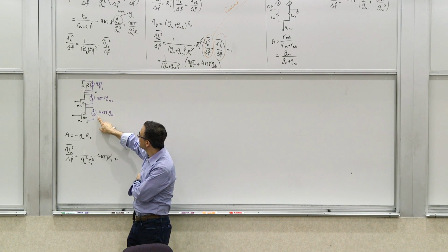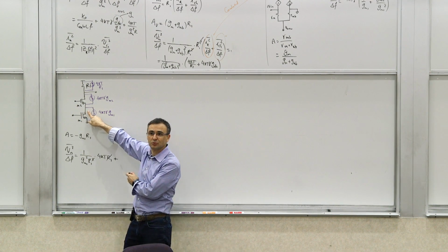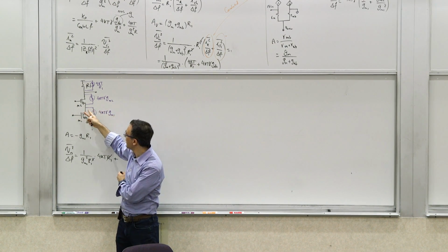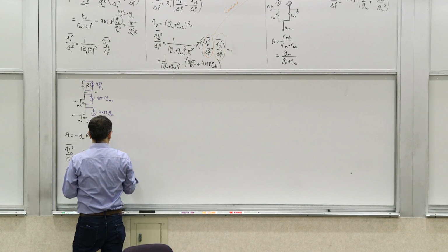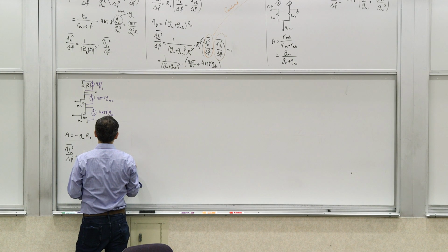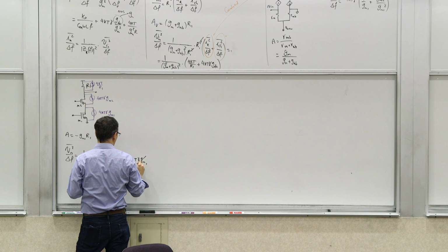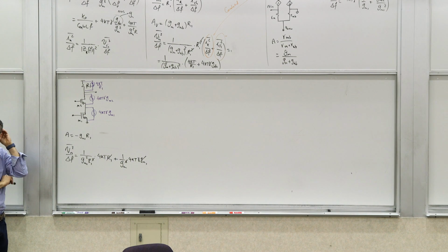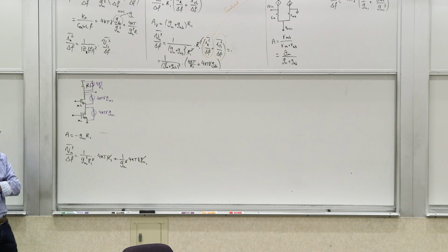Now, how about this guy? Whatever you see here, you could put a voltage source here, and this voltage gets multiplied by GM of this thing to produce this current. So to reflect this to the input, I have to divide it by GM1 squared. So I get plus 1 over GM1 squared times 4 KT gamma GM1. One of them cancels, and you're left with that. That's the contribution of those two, which are more straightforward. The question is, what is the contribution of this guy to the input?